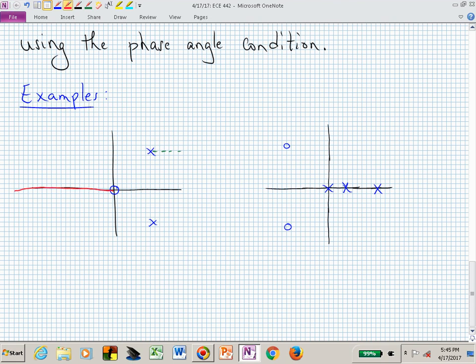If you know where this pole is and you know the zeros at the origin, you can find that radius. Once you have that radius, you're now good to go relative to knowing the structure of 2 poles and one 0. In this case, you now have this radius there, and using your compass, that would be a circle. You're departing from the two poles, and you re-enter a radius away from the origin.